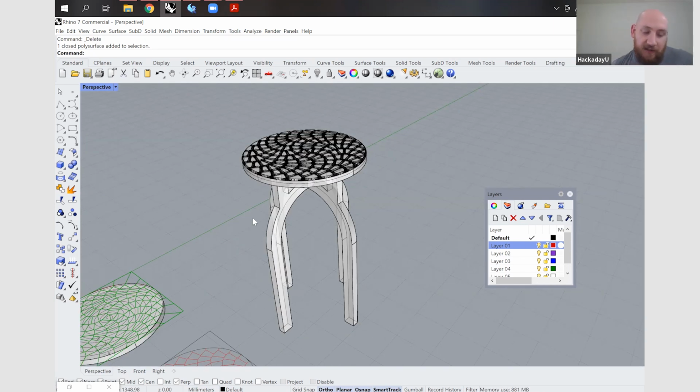Plywood can expand depending on the season, and it's kind of a trial and error process. Sometimes the CNC, especially since I use a ShopBot, some of the machines are more accurate, sometimes they're a little off. So I do a few tests and see how that goes, then apply that tolerance to the rest of the geometry and recut. I wouldn't take a file and cut it directly without doing a tolerance check.